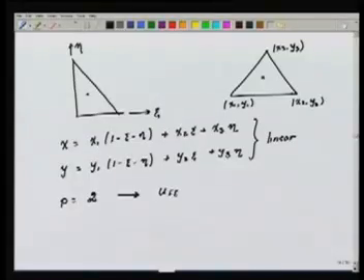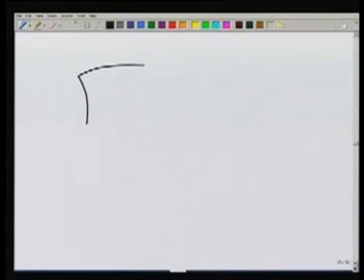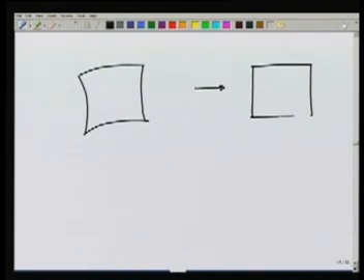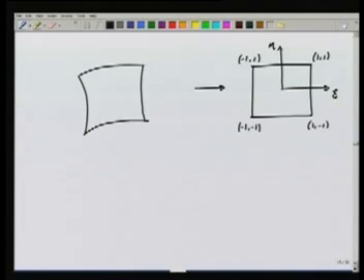Now, there could be a situation, which is very popularly used, where I have this kind of a curved element, which maps to this master element. If you remember, this is the point minus 1 minus 1, this is the point 1 minus 1, this is the point 1 1, and this is the point minus 1 1. So these are the 4 nodes: node 1, 2, 3, 4. If I did just using these 4 nodes, then I'll end up getting this representation, that is, the curved edges will not be properly represented.